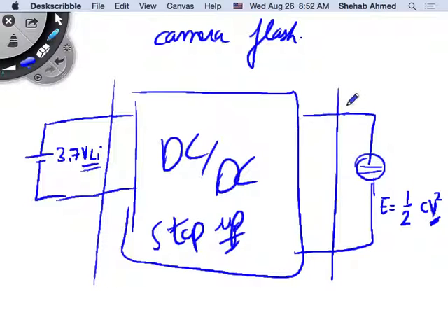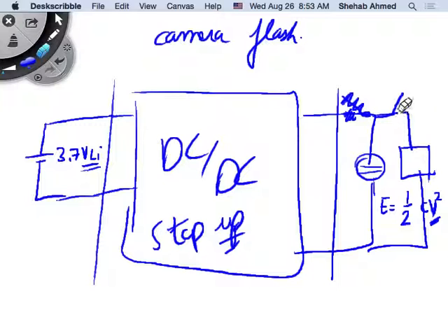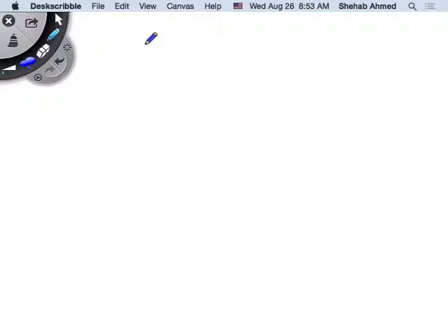So that's something that you would need to do. So you would typically have a switch here. Of course, whenever you charge the capacitor, you have your camera flash, I don't know, somewhere here. After that, sorry, put the switch after the capacitor. So you first charge the capacitor with your power supply. When it's charged, a switch will close to connect your capacitor at very high voltage now to your flash. And you will ignite the flash and take the picture here. So that's another application.